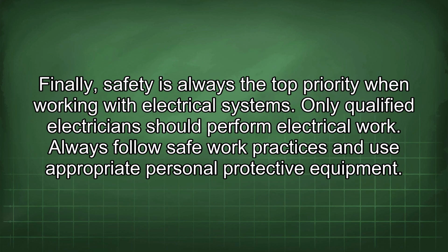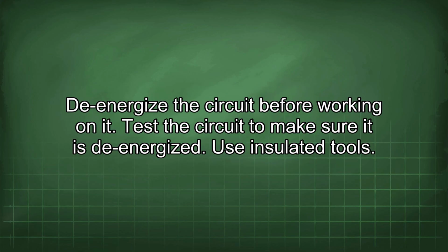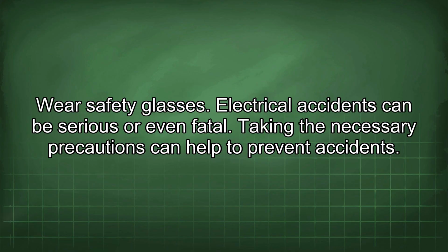Finally, safety is always the top priority when working with electrical systems. Only qualified electricians should perform electrical work. Always follow safe work practices and use appropriate personal protective equipment. De-energize the circuit before working on it. Test the circuit to make sure it is de-energized. Use insulated tools. Wear safety glasses. Electrical accidents can be serious or even fatal. Taking the necessary precautions can help to prevent accidents.